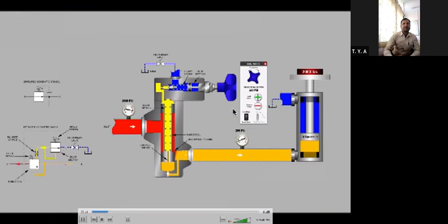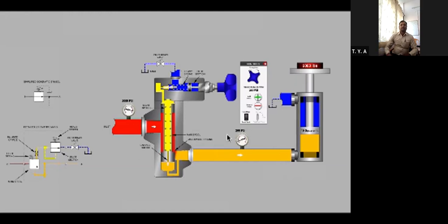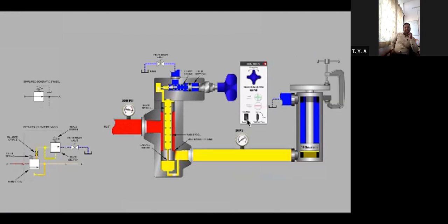This is part 1 on a pilot-operated pressure reducing valve. A pressure reducing valve is used to step down a higher system pressure to a lower maximum value in a downstream subcircuit. The internals of the valve don't really become active until there is considerable resistance on the outlet. The valve is not intended to be used as a flow control. It is a pressure control that can be used to limit the mechanical force of an actuator such as a cylinder.